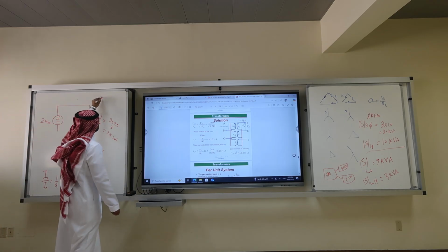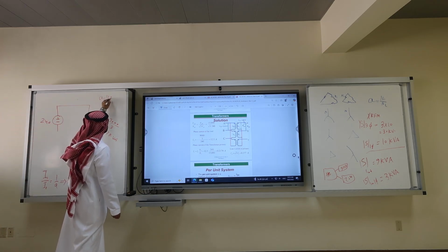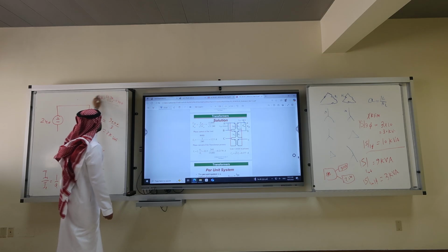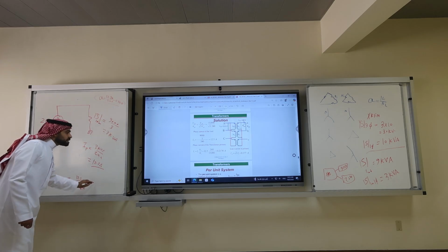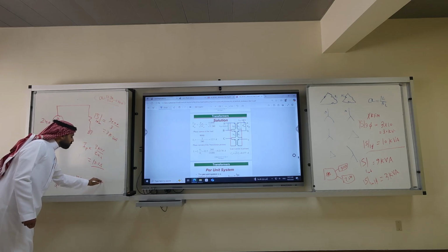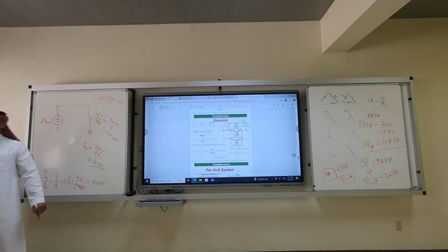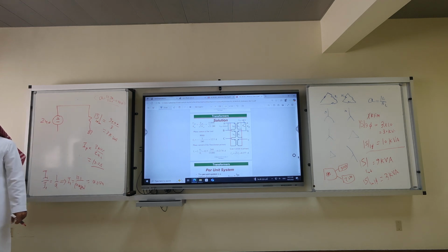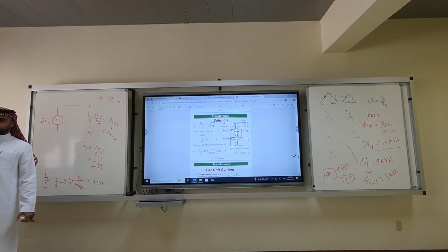You remember your A? What is A? 13.8 kilo over 240, which is what? 57.5. So that's why you get a very small current of 0.2174. If you get a bigger current on the higher voltage, there's something wrong. Okay? Remember.